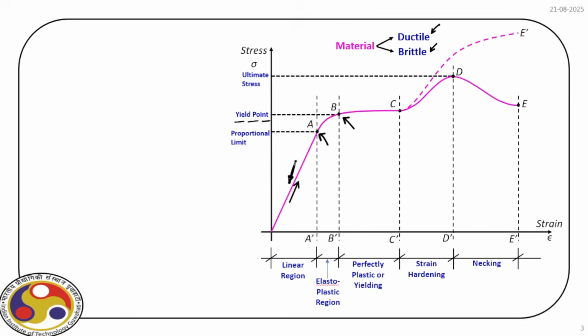And we definitely do not expect to have permanent deformation in the material, because if it is well within this proportional limit, we can load and unload the structure and use the same structure without having any permanent deformation, right? So this yield point, where the stress is sigma y, is actually the point crossing of this point. We consider it to be a failure.